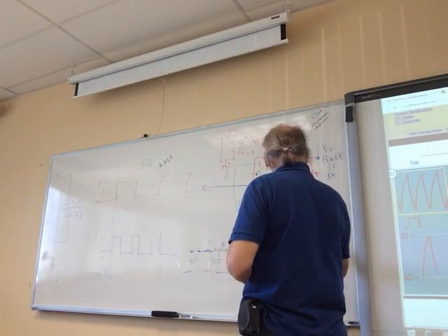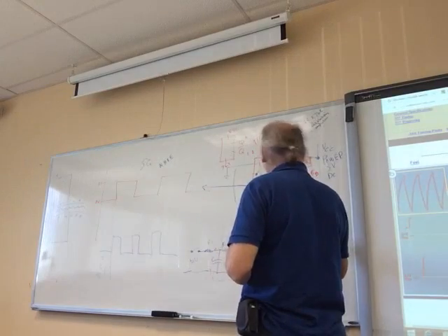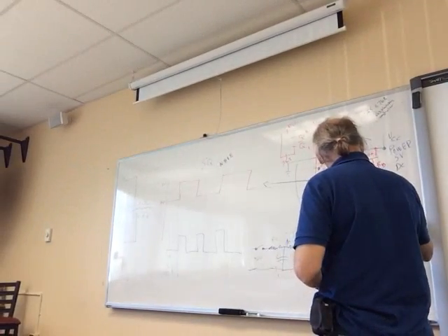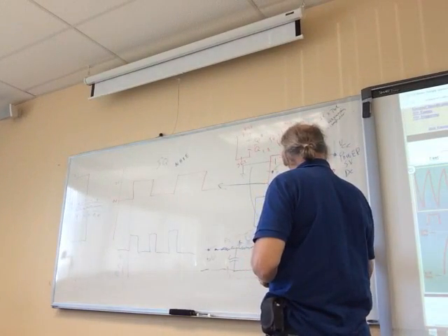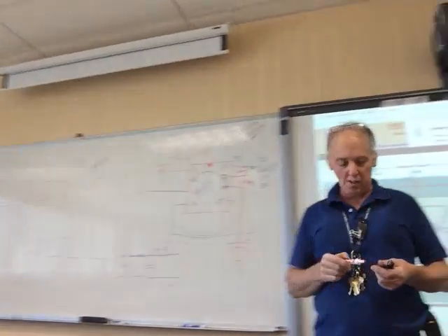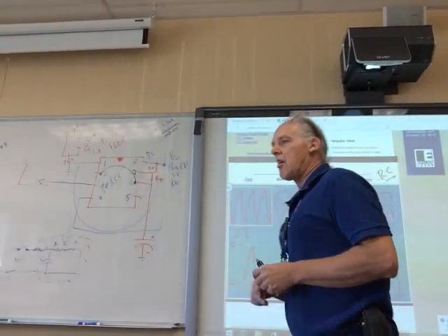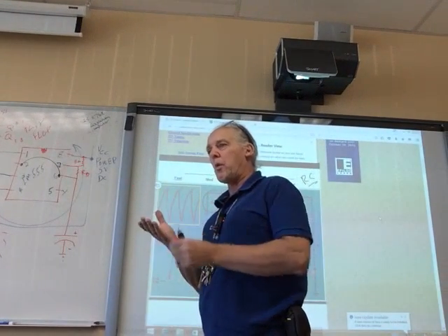By the way, this designates an electrolytic capacitor, which means this side is plus and this is minus, and that's correct because the minus is on ground. We don't have to use an electrolytic. We can just use a standard ceramic capacitor with no polarity, okay?